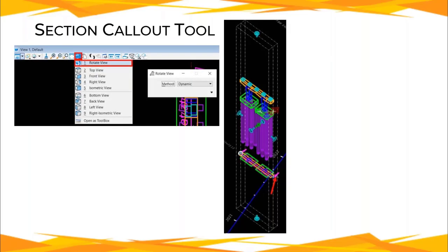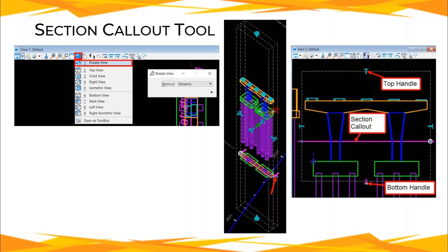So the best way or easiest way to do that and grab these handles would be from like a front view. So you can do like a shift right click, F for front or S for side, and just get an easier view to manipulate the handles of the clip volume and know where those handles, the boundaries for that handle, are relative to the elements that you care about. So in this case, I want to cut those pile off, right around here. So I'm going to drag that handle up to this point here.